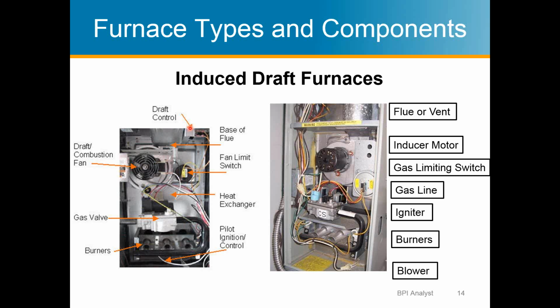It's telling you what percentage of the heat you are taking out of the combustion process. So here you're getting 98% of all the useful heat out, and you're losing 2% of the heat that would go out of the exhaust.